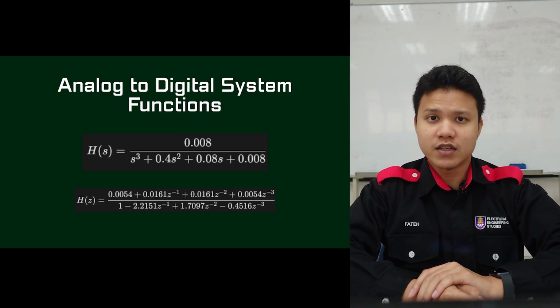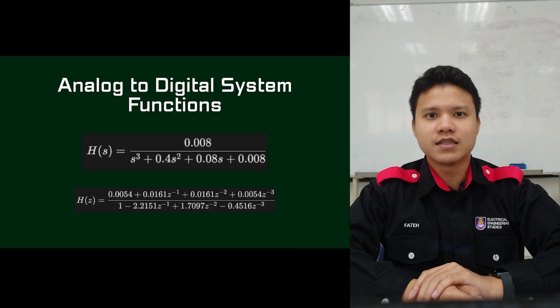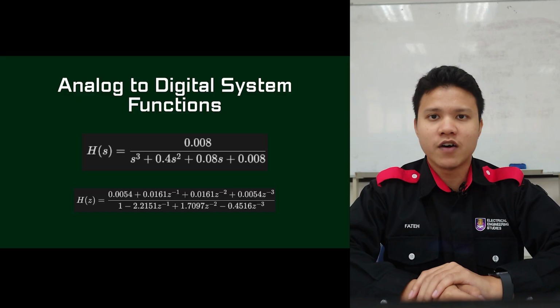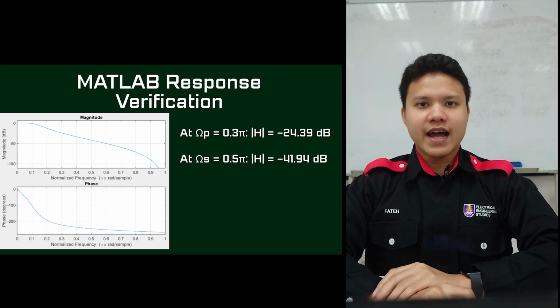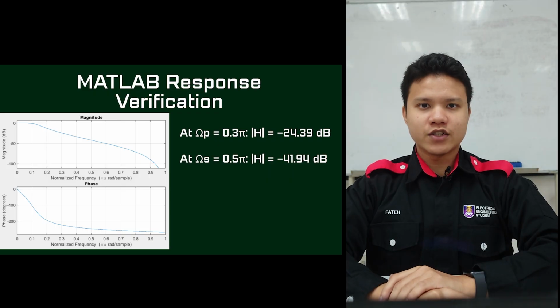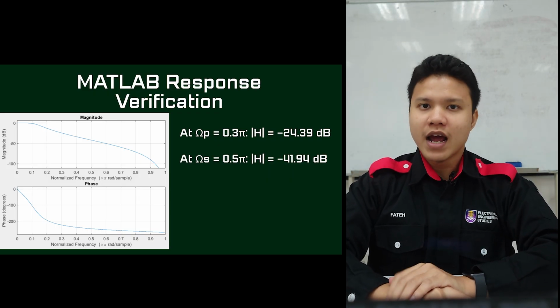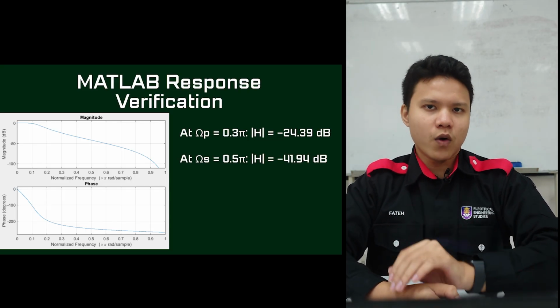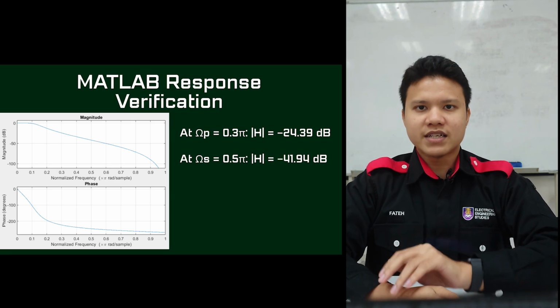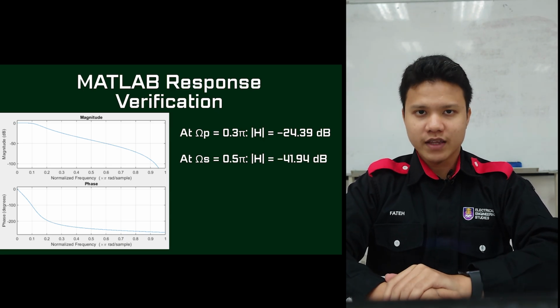They map perfectly to a symmetric 1:3:3:1 ratio, which is the binomial signature of a robust Butterworth low-pass design. To verify our design accuracy, we ran a validation script in MATLAB using the buttord, aka Butterworth filter order, and butter routines. MATLAB independently confirmed an order of N equals 3, matching our manual calculation perfectly.